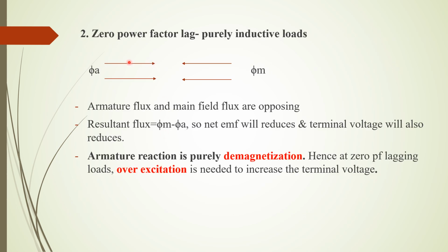The second point is what will be the armature reaction at zero power factor lag. Zero power factor lag means it will be purely inductive loads, then zero power factor lead means purely capacitive.